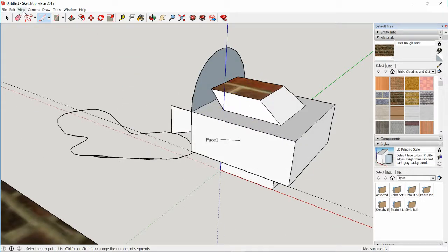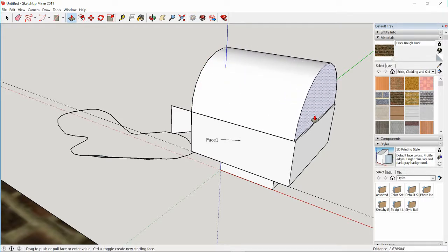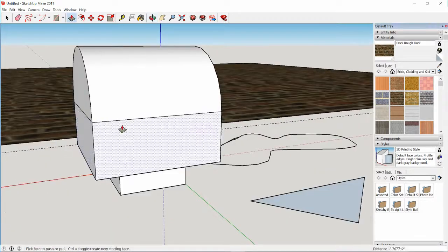And then if I wanted to, I could get rid of this stuff here. Whoops, but I don't want to get rid of that. Escape. So then I could extrude this, and then you have a somewhat dome. And it'll snap if you highlight over this edge, then it'll snap to that edge. So then you know that you're lined up perfectly.